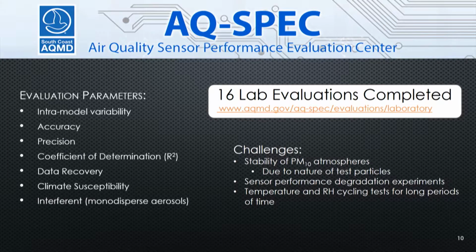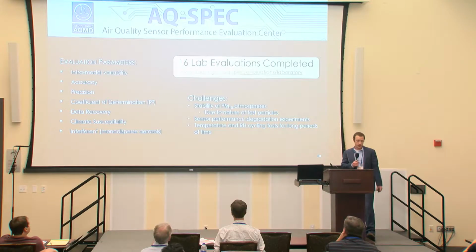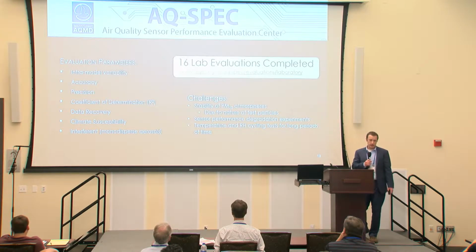Some of the challenges we have encountered through developing the protocol and the system are the stability of large particle environments, the PM10, and part of that's due to the nature of those test particles. Also, sensor degradation performance is difficult to assess with long-term tests, and temperature and RH cycling tests for long periods of time are challenging.